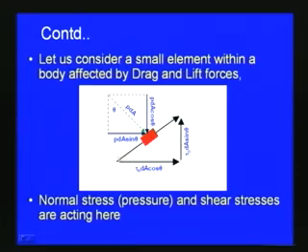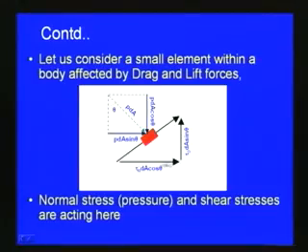and in the normal direction it will be P dA cos theta. Similarly, if you consider the shear stress, with respect to the viscous fluid, there will be shear stress on the body. With this angle theta, in this direction the shear force will be tau 0 dA cos theta, and normal to that, in the upward direction, the shear force will be tau 0 dA sin theta, where tau 0 is the shear stress acting on this elemental area.